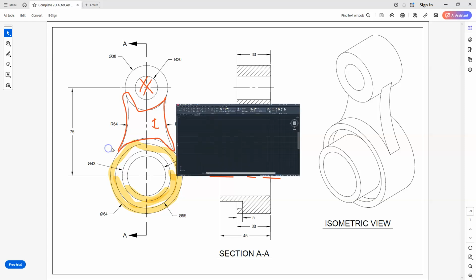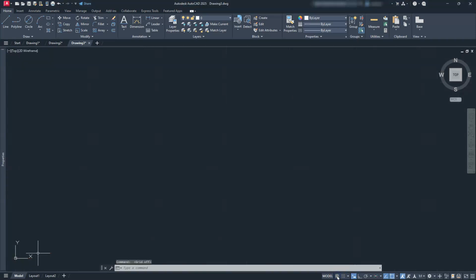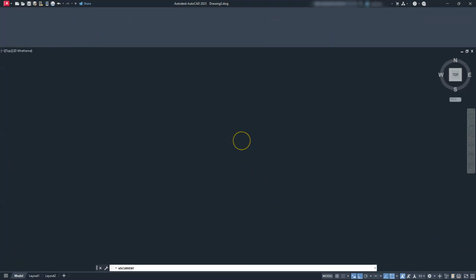Okay, so let's go ahead and do our normal stuff that we usually do here. We'll go ahead and turn the grid off, and we'll click that button here. We'll go ahead and put our ortho on. We'll take a look at what O-snaps I have turned on. And then I'm going to switch over to the 3D modeling. So I'm just going to use the 3D modeling one here. Go ahead and give it a second. Your ribbon should switch and you should get another dialog box.